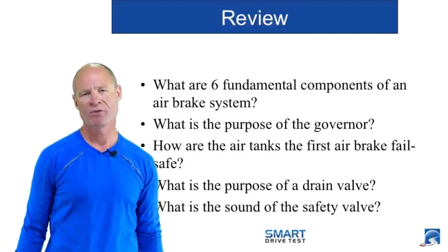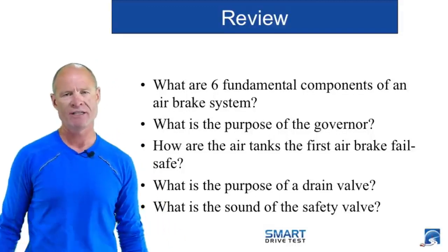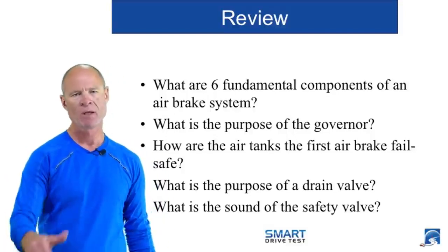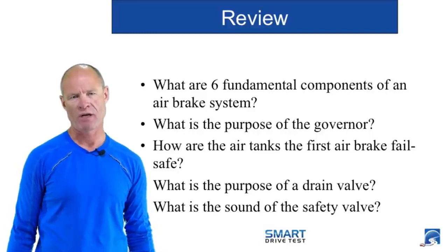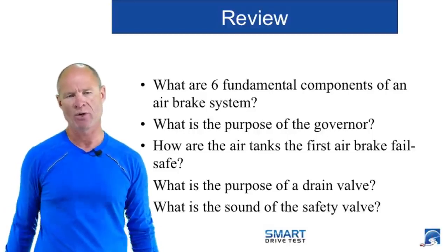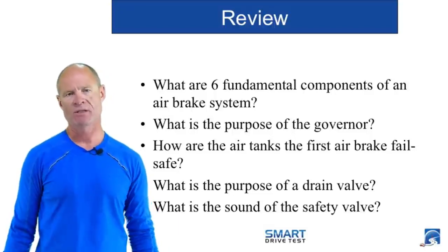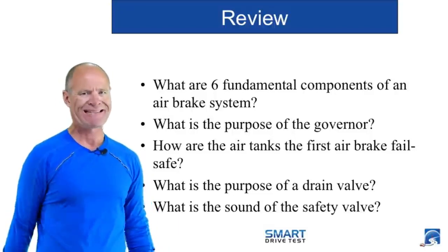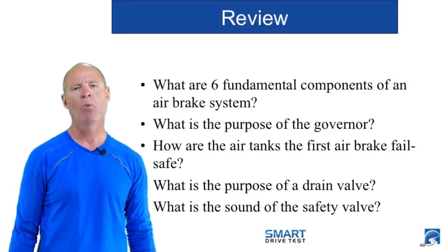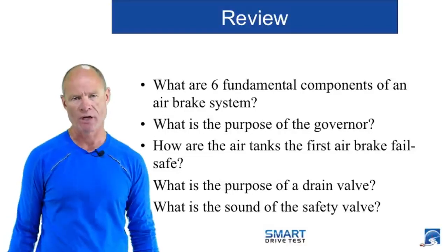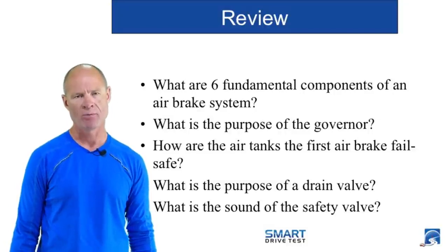Question: what is the purpose of the drain valve? The purpose of the drain valve is to drain water from the air tanks so they don't freeze up and cause damage to the air brake components, and also to remove other sludge that is discharged from the compressor, and some of the dirt. Question on the test: how often do you drain wet tanks? The answer to the question is daily. Every day you drain the tanks on an air brake system.